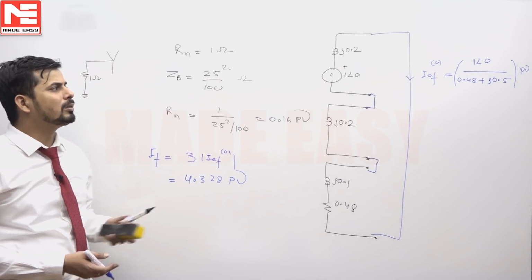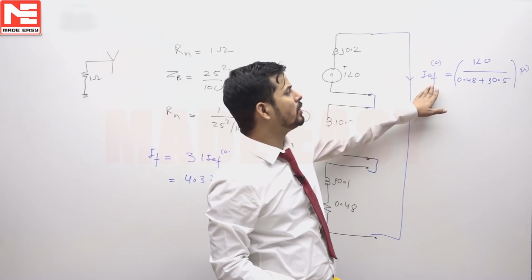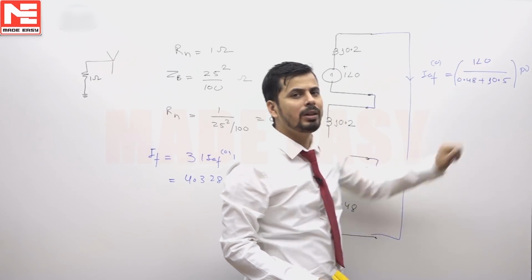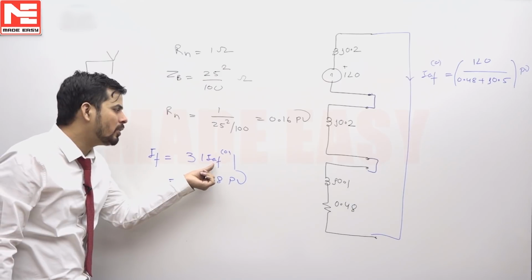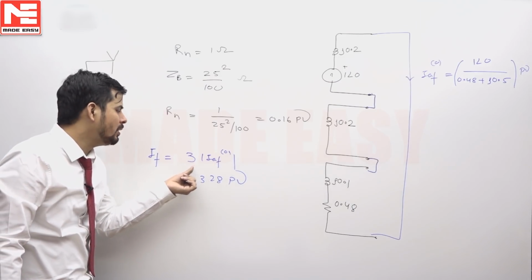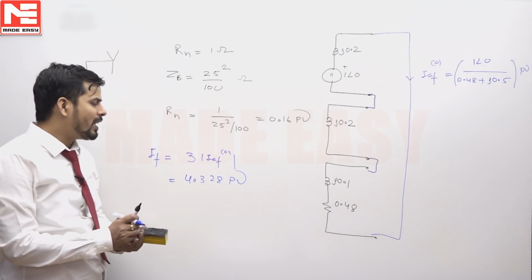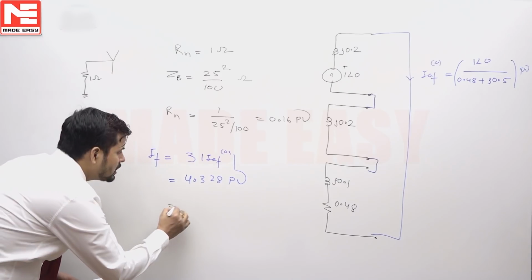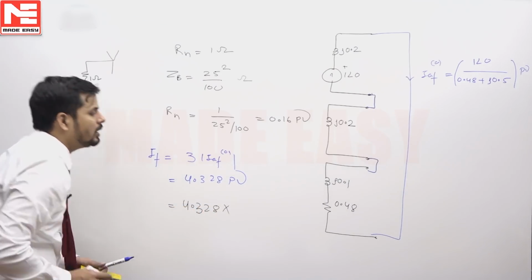How have we calculated it? We have calculated IAF0, taken the magnitude of IAF0, and multiplied it by 3 to find the fault current value. This is the per unit value of fault current. To find the actual value of fault current, we will multiply this per unit value by the current base.